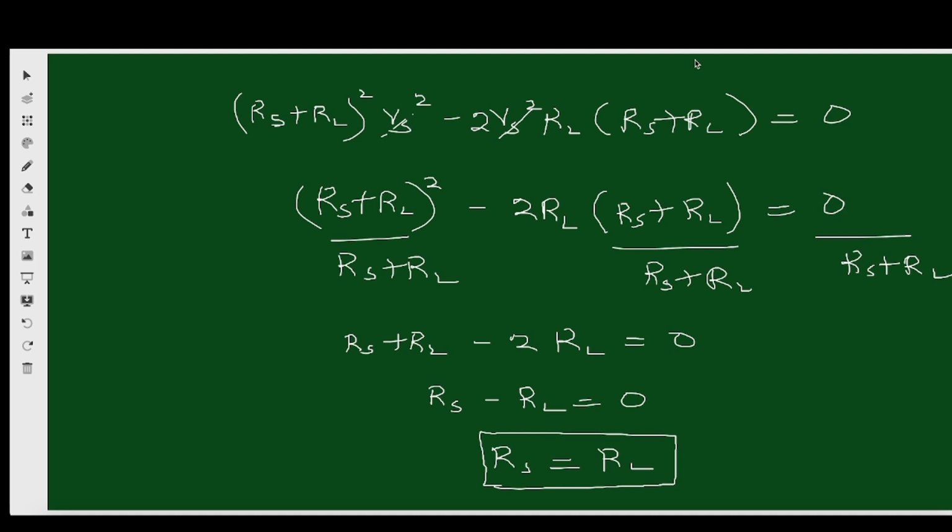An alternative way to view the maximum power transfer is possible in terms of the Thevenin equivalent resistance of a network. A network delivers maximum power to a load resistance RL when RL is equals to the Thevenin equivalent resistance of the network. That's just very, very simple. So like I was saying, this Rs in terms of Thevenin is the same thing as the Thevenin equivalent resistance. I hope that you understand what I've explained so far.